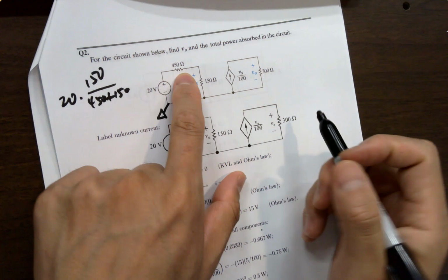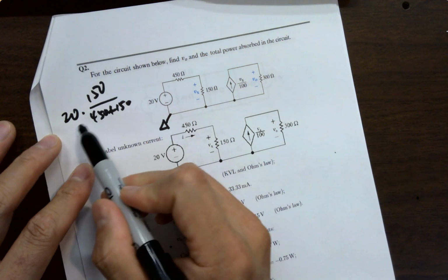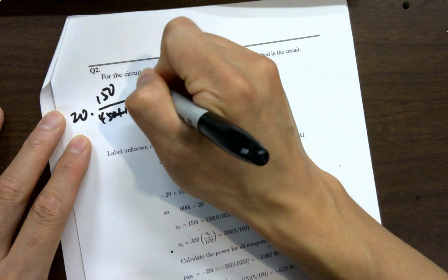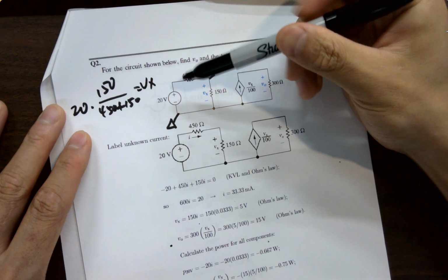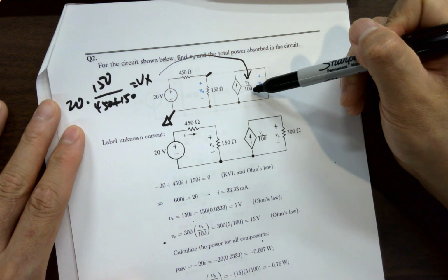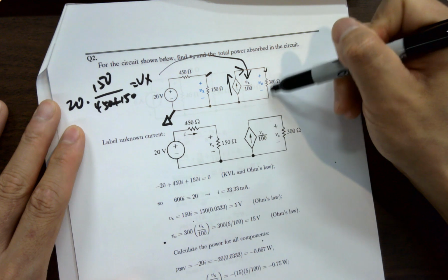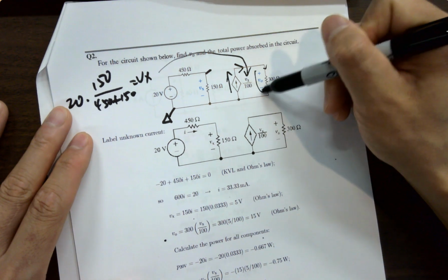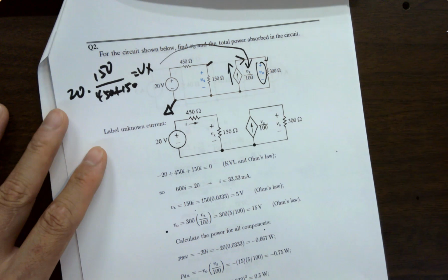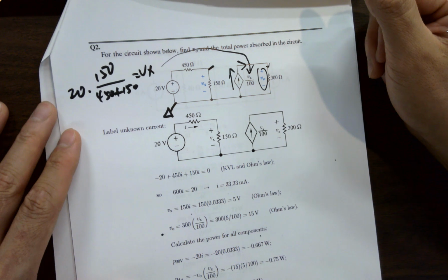Okay, but here, do they share the same current? Yes, just one mesh, one branch. So you can definitely use the voltage divider theory to find the voltage here, which is Vx. When Vx is calculated, I just plug in here. It's just one variable. So Vx divided by 100 gives me this current, so I can calculate the current. If I get a current, the current flows through this 300 ohm resistor, and I get a voltage V out. You don't even need the KVL and all these. All right. Make sense?